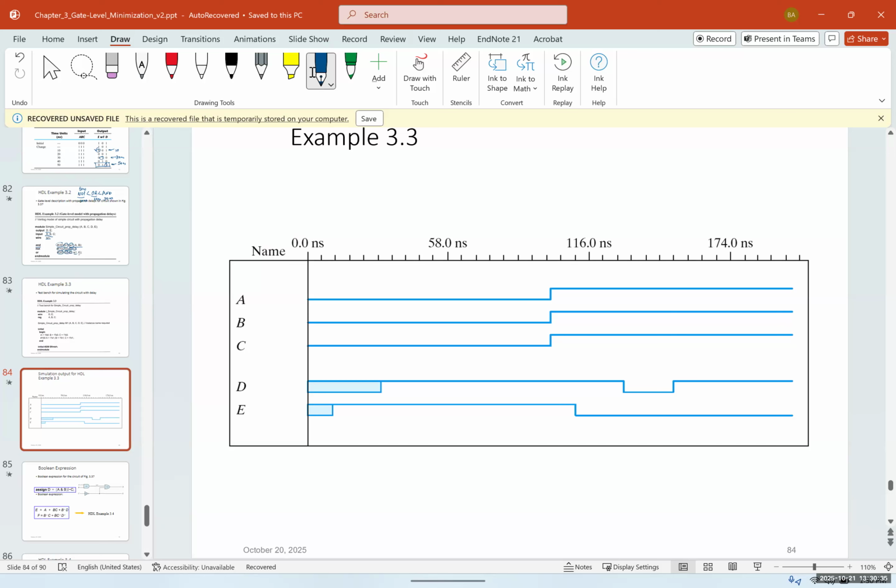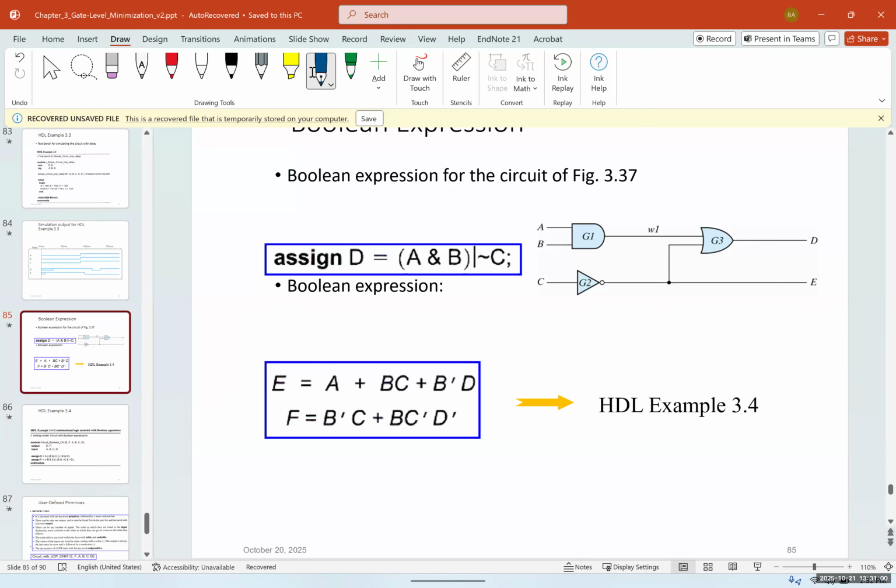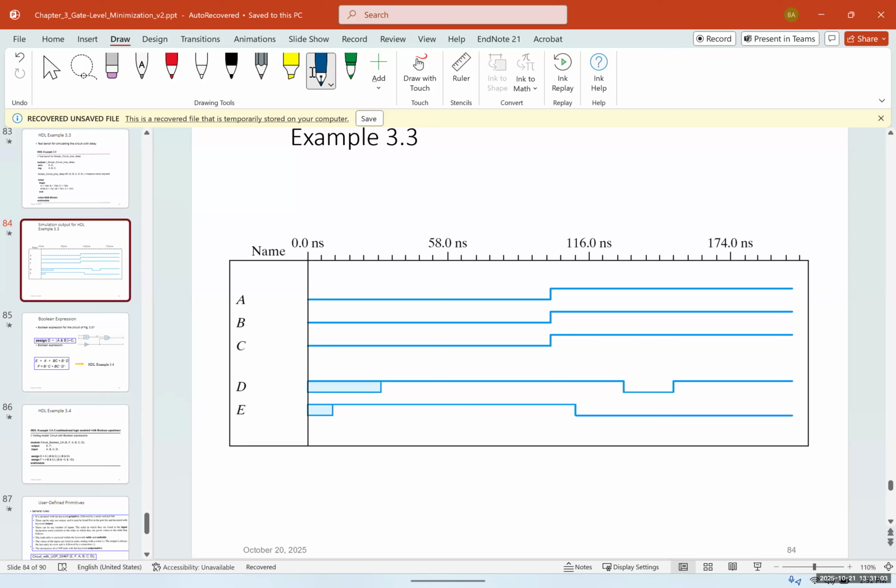Again, when you are solving this with a simulator, like an HDL simulating tool, if you don't see any results initially because of the propagation delay, you just have to scroll forward, and in most cases you will see where the signal has reached its steady state and the final output. Where are those bars at the beginning? Oh, these are the propagation delays that you have from the AND gate and the OR gate and the NOT gate and so on.